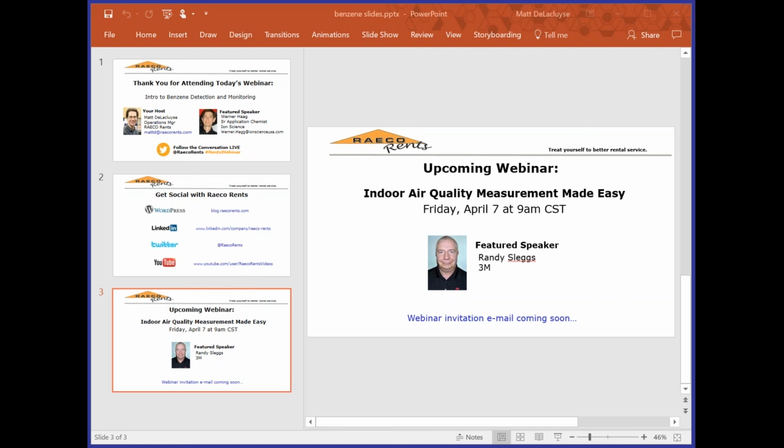Can I add one more comment? I think it might be important to note about humidity, that these tubes do contain acids, and the tubes are not affected by humidity, so you can actually make measurements in steam. But don't do that very long, because you can generate liquid acids that can get sucked into the instrument and damage it. The tubes turn a dull orange color when they're saturated with humidity, and at that point you should stop using them.